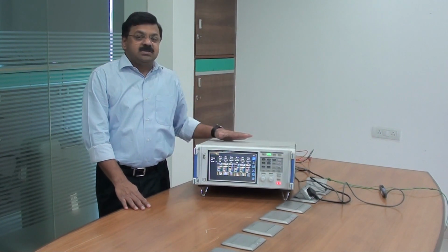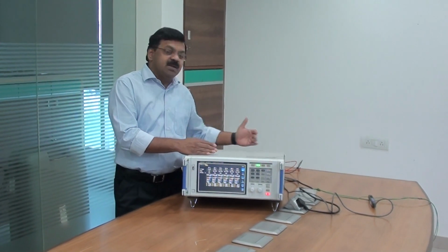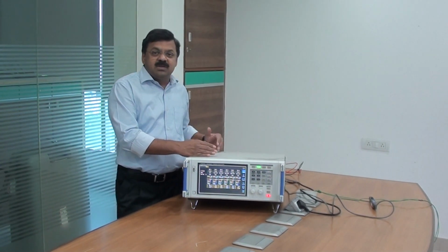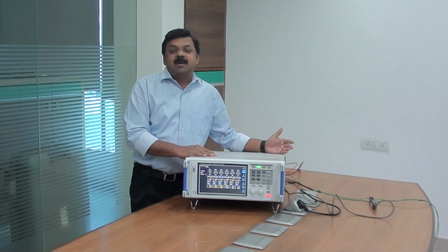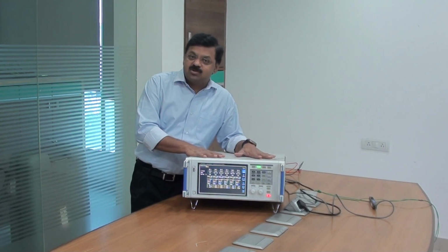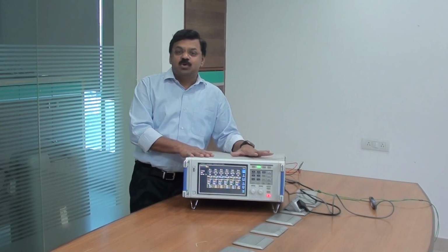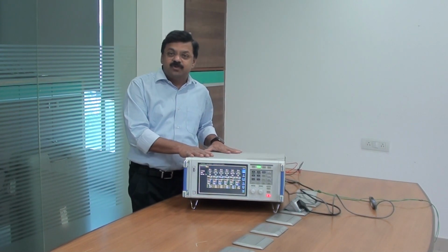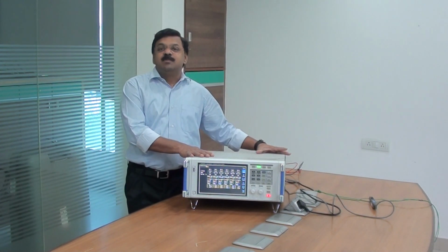Yeah, so once you have configured the system with the number of channels, you have seen the input section. After you configure this instrument and depending on your applications, the applications that this instrument can cater to are transformer core loss, inverter test, drive test, inverter efficiency, motor efficiency, and so on and so forth. LED test and solar test can also be input.